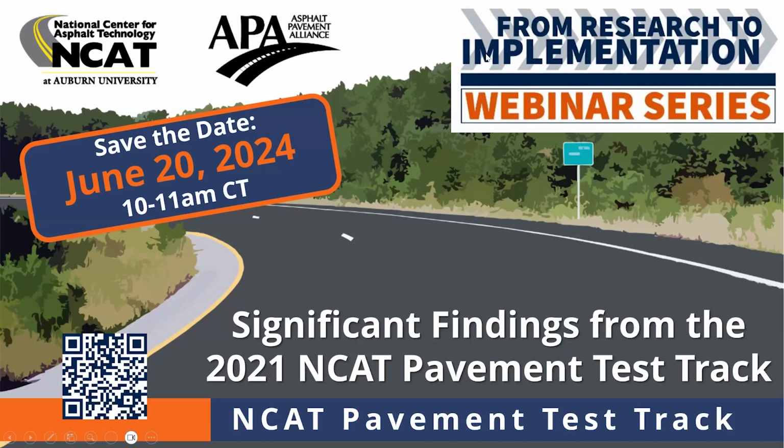We did a forensic study in the laboratory, where we had shot a kind of textbook range of tack at a 0.06 rate with the emulsion that we were using. What we found was we needed a 0.1 rate. So that experiment really changed my philosophy on tack. When we're doing studies, and we don't want the studies to be confounded by tack, by interface failures, I'm going to shoot a 0.1 with an emulsion unless there's a compelling reason not to. And if I'm shooting a hot liquid just with a dense graded mix, I'm going to shoot a 0.06. So I think a 0.06 residual rate is a really good place to be.